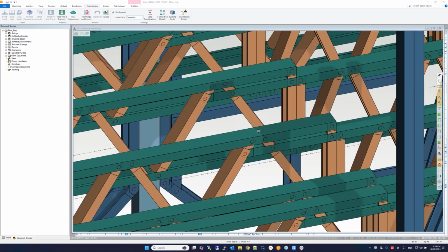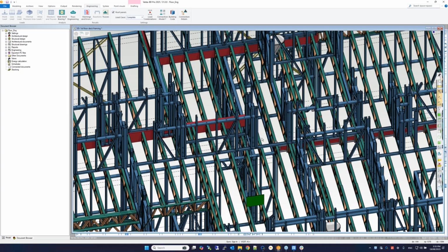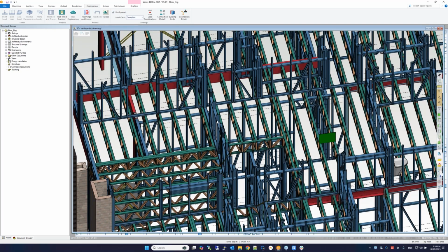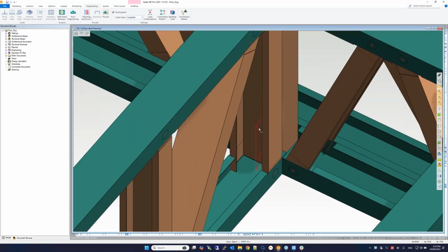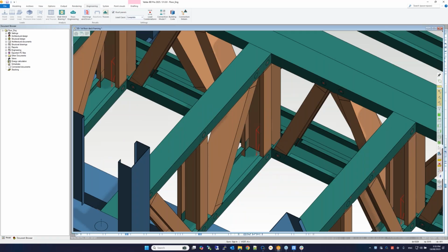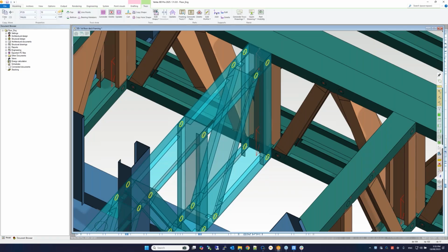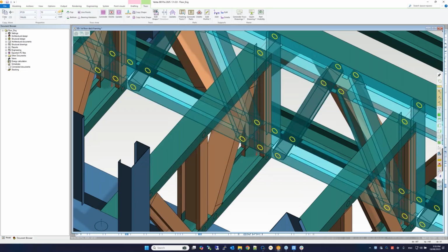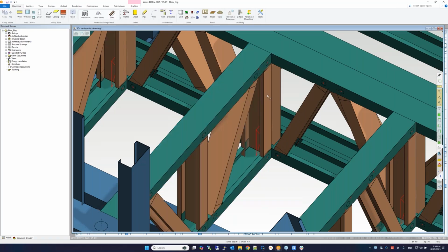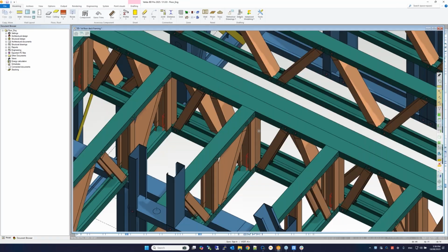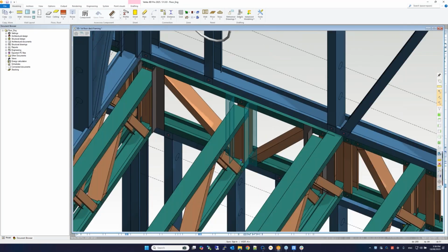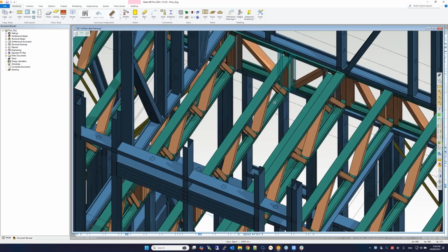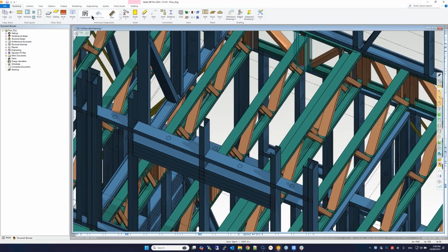There's a question regarding the connection between trusses. I'm not sure if you're asking like this. If you can see this red box, that's the screw pattern, but this is only a joint between these trusses to tell the software that this truss is being supported by this one. It's not engineered during the engineering process. And you have different options in the software. Like you can also use these brackets, and I think there are more in the drawing library and this component.